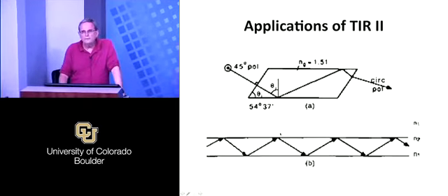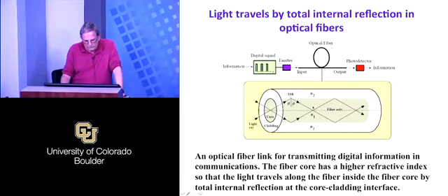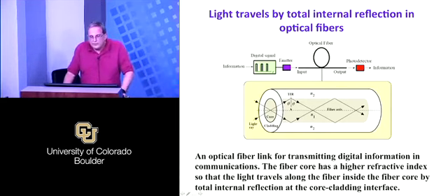I think he was the first guy who did this for another type of experiment, where he guided inside of a higher index medium. This also is an optical fiber, evidently. In an optical fiber, what we do is dope the silica core with a little bit of germanium to raise the index of refraction. And these things evidently will guide for hundreds of kilometers. Here's a picture of one in 3D of a step index fiber.